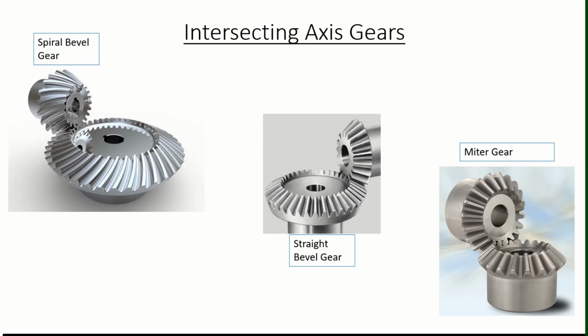The spiral bevel gears are superior to the straight bevel gears because there is a high contact of the meshing teeth from both gears, and that reduces the vibrations and noise, and also adds to the strength as well as the higher efficiency. But at the same time, they are more difficult to produce, and because the teeth are curved, they also cause thrust forces in the axial direction.